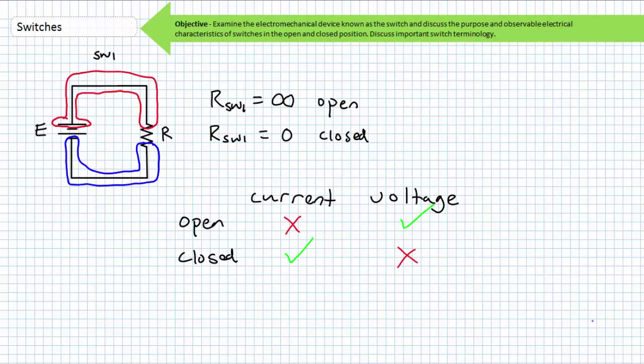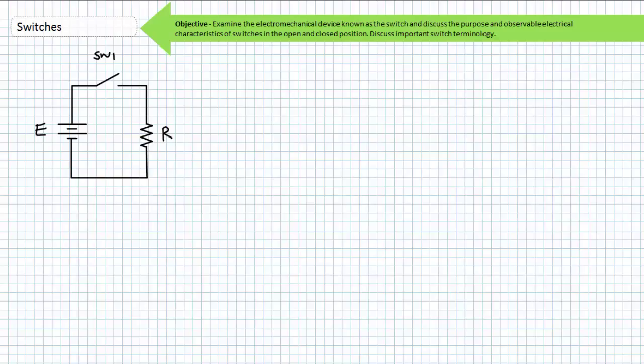For the case of a closed switch in series with an electrical load, all voltage will be dropped across the electrical load. Pause to contemplate the physical construction of a switch and the numerous environments it might be employed. Obviously, a switch must be built strong enough to handle the current through it and the voltage across it. You can't expect a tiny dip switch used on a protoboard to make or break the current to a large industrial motor, and the use of sulfur hexafluoride switchgear ordinarily reserved for a large hydroelectric dam might be a bit